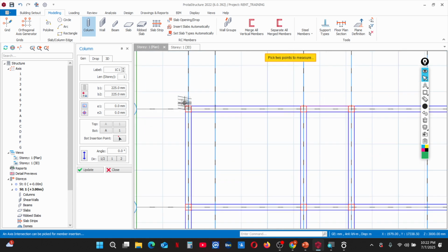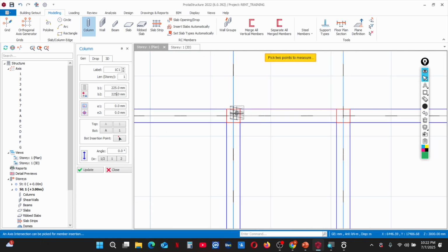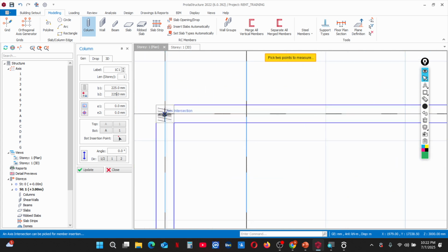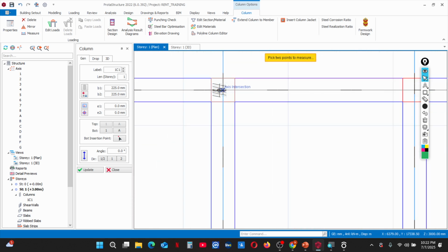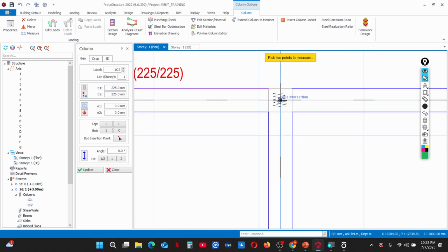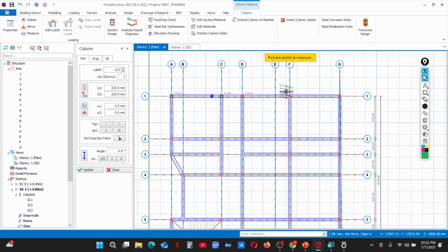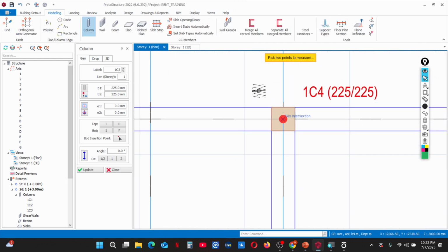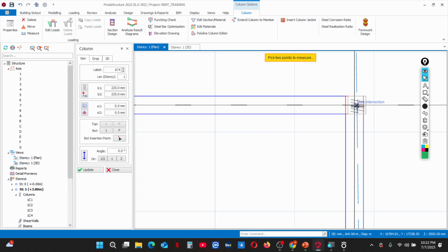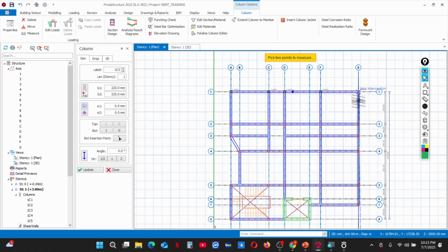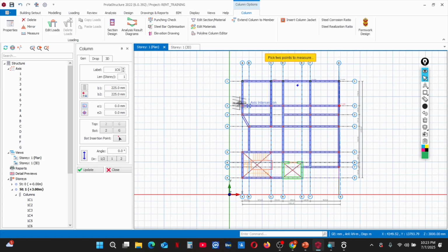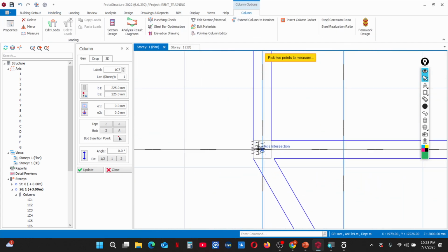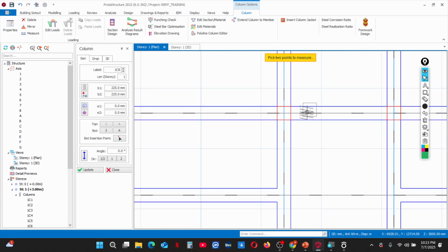Then you can be tracing all these thread points where we have these red squares. That is where you are going to be placing your columns, just like so. This is what I want to see in your assignment. When you have selected and added your external reference drawing, create your grids just like so. After creating your grids, you can start inserting your columns at the axis intersections where we have them. Those points are the places where you insert your columns.